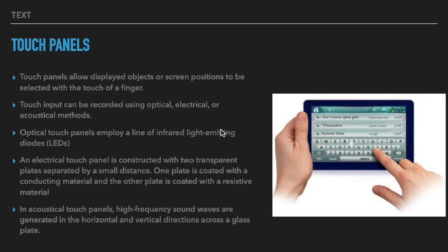Okay, the optical touch panel employs a line of infrared light emitting diodes, or LEDs, along one vertical edge and also along one horizontal edge of the frame, and opposite to these LEDs, there will be light detectors on the other vertical and horizontal edges.